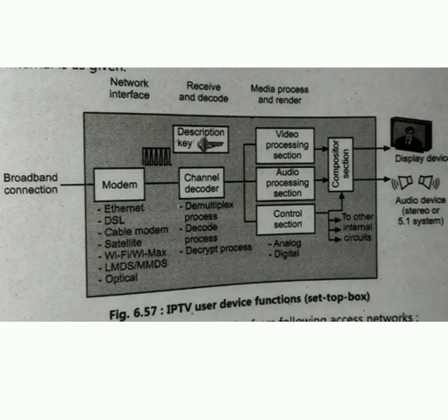Further, we can have the IPTV set-top box along with a smart card system, where we insert a smart card into the set-top box, and different keys are given for that set-top box. The same processing is done: we demultiplex and decode the signals and get the video, audio and control signals, which we transmit to the display devices and audio devices, so that we get the output at the receiver. The only difference is that we have a smart card and a key for the smart card.